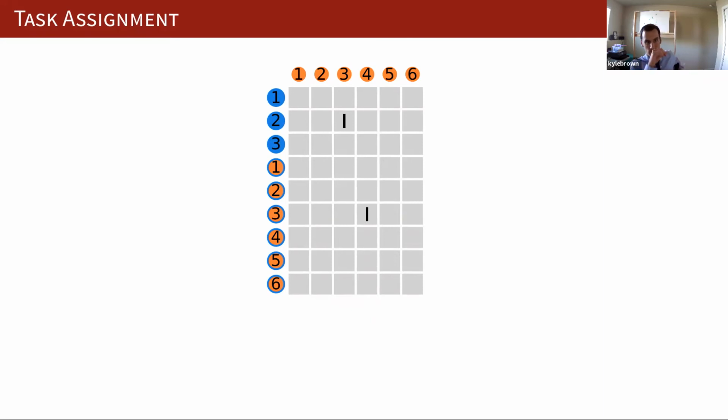So now we have converted our time-extended assignment problem into a one-off assignment problem by using this simplification or this transformation where we assume robots disappear and new robots appear.